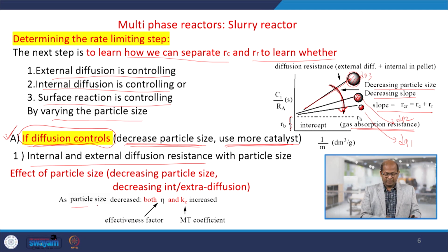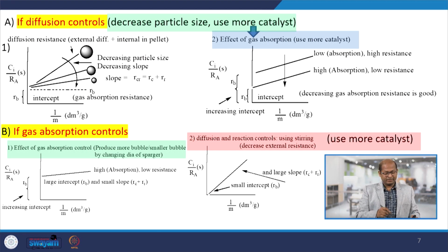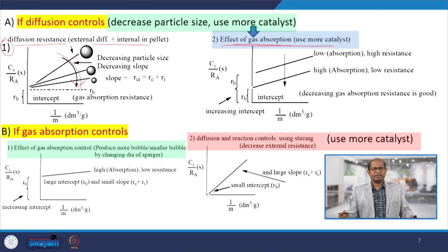Okay. As the particle size decreases, what would happen? The eta value and Kc value both will be affected. Both eta and Kc will increase. If we decrease the particle size, the effectiveness factor eta will increase, and Kc, that is the mass transfer coefficient, also increases. So, here we are decreasing the particle size this way, and gas absorption...